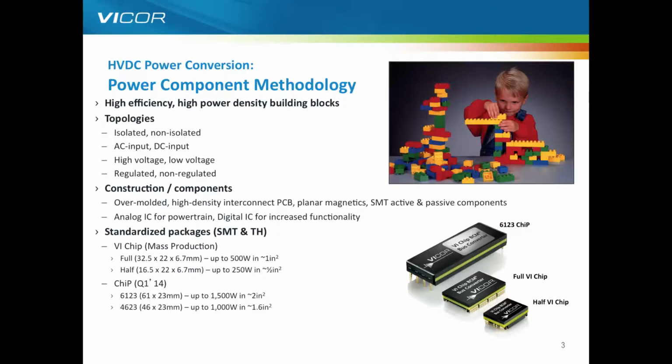Physically, those devices are highly integrated electronic components. They have multi-layer PCBs with planar magnetics and then active FET silicon and also analog and microcontroller ICs, plus a bunch of discrete resistors and caps, which are overmolded to form a nice smooth surface if heat sinking is required. And the overmold also acts as a heat spreader for any hot spots within the devices.